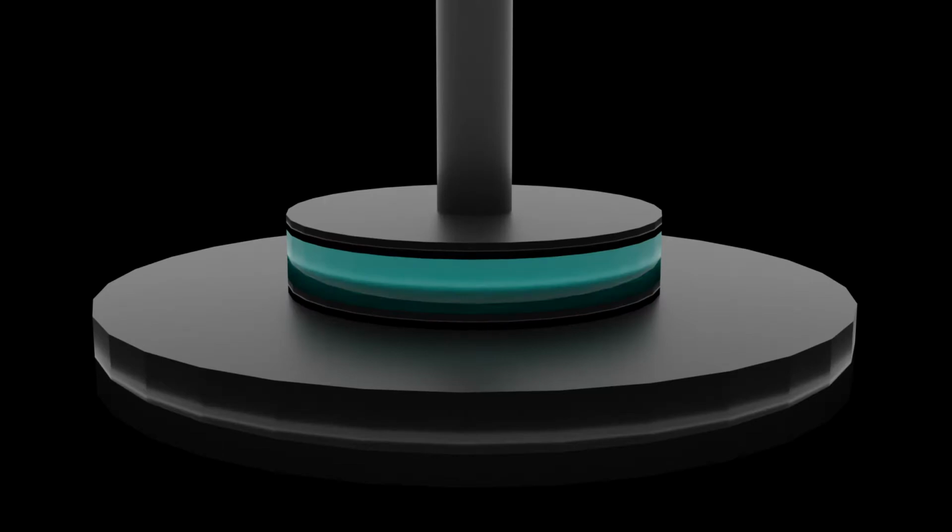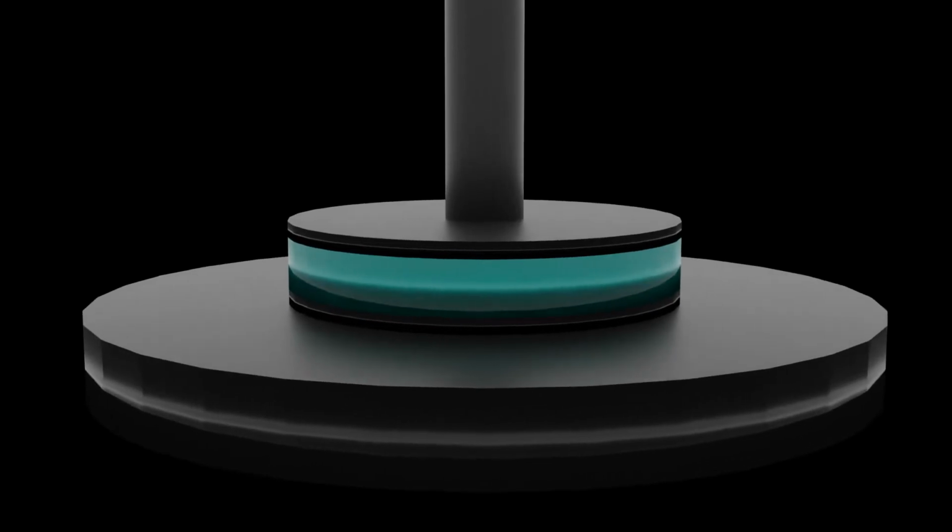One of the ways to measure these quantities of a fluid is to use an instrument called a shear rheometer. The fluid of interest is placed between two geometries, which can be flat plates, cones, or other shapes. The surfaces of the geometries can also be smooth or rough. Here, a shear rheometer using two smooth flat plates is shown.